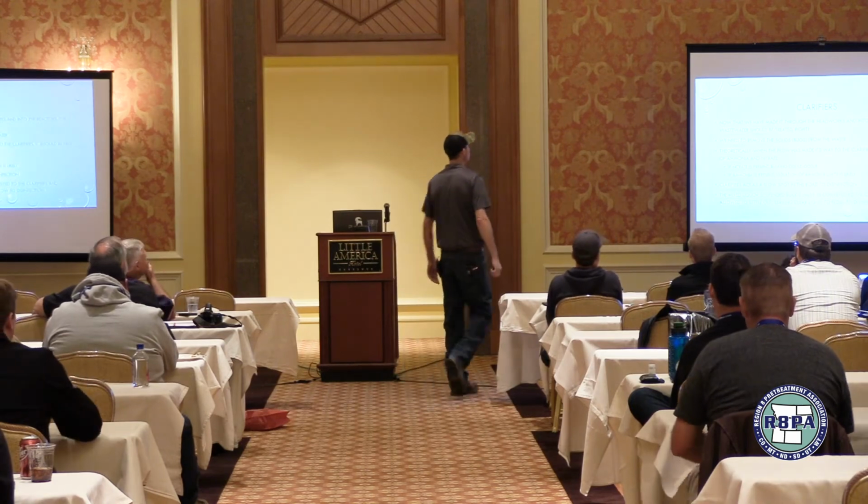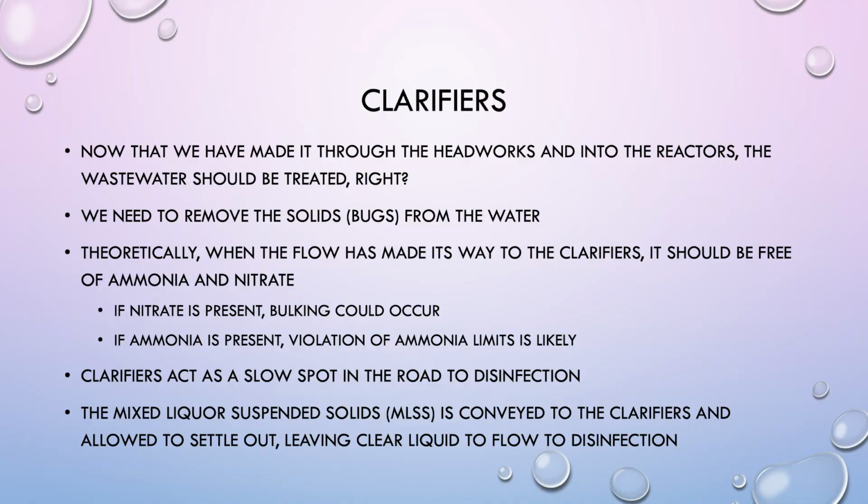Clarifiers. We made it through the headworks, we're into the reactors, the wastewater is treated now, right? Went through the headworks, got the magic, the bugs are in it, now we're in the clarifier. What happens in the clarifier? We talked about it a little bit. Slow spot in the road. Let them settle. Let my bugs settle.